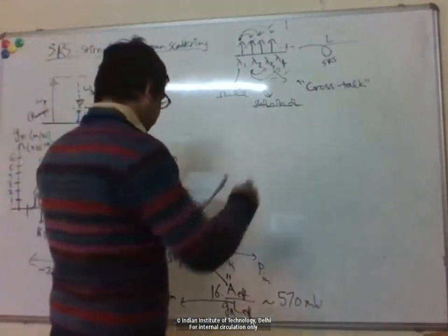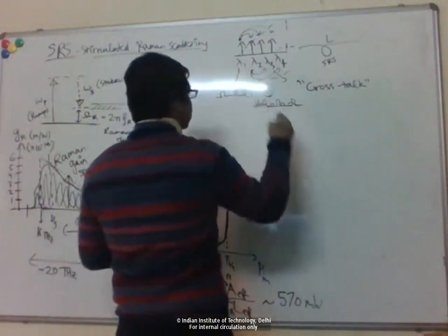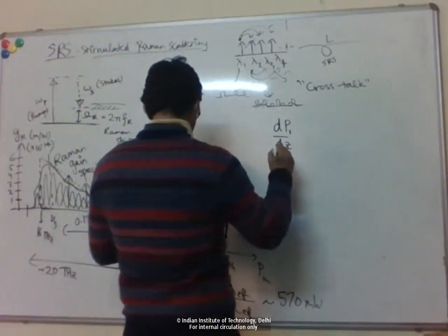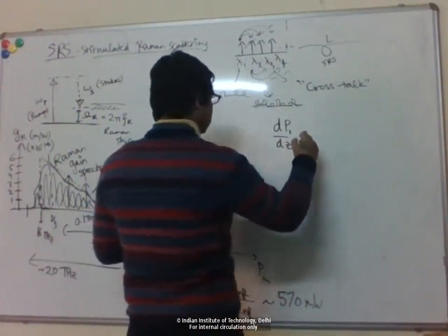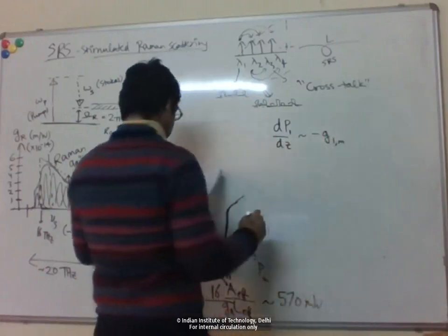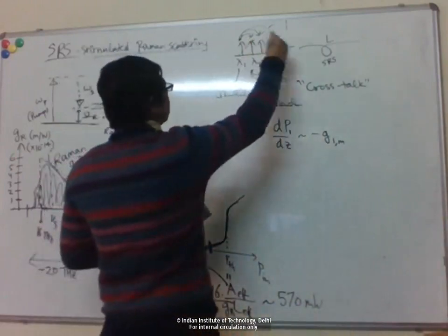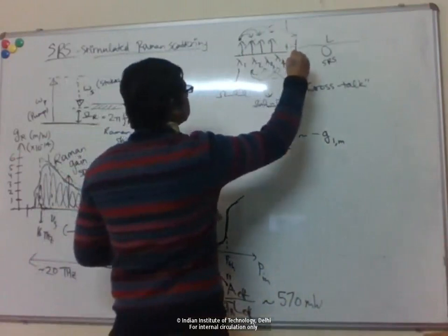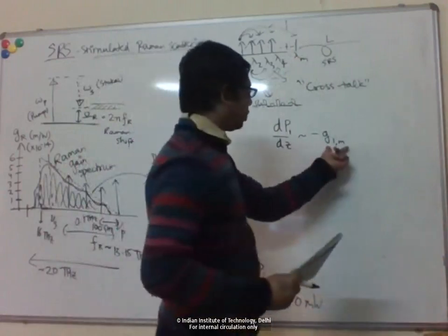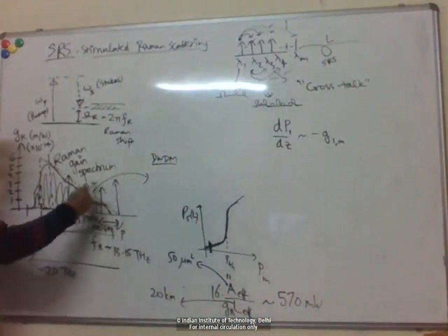Okay, so again, if you look at this propagation equation, if I look at the first channel, for example, the power in the first channel, so if I look at the power transferred from lambda 1 to some lambda m-th channel here, that will be proportional to the gain coefficient, which depends on the difference between lambda 1 and lambda m.